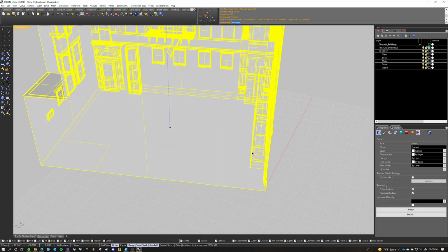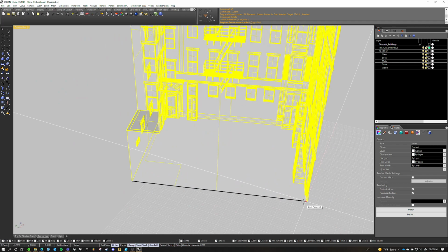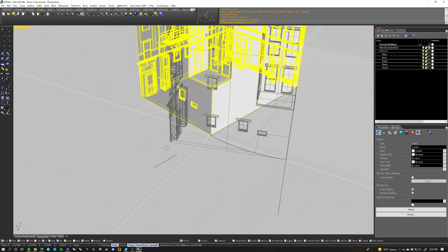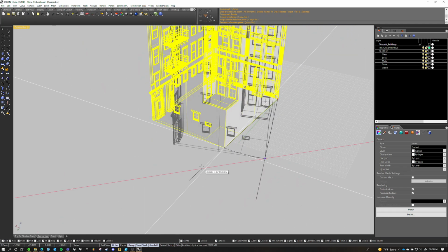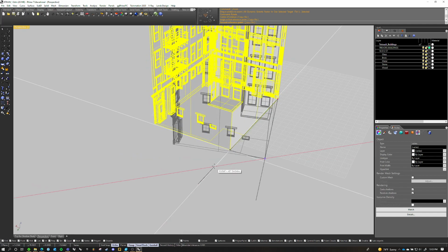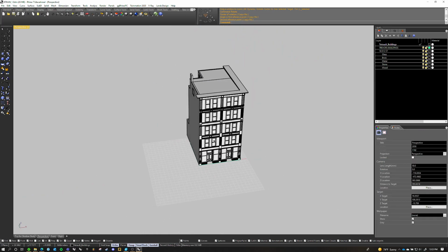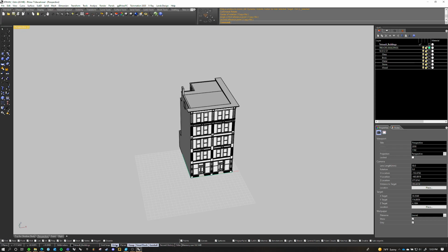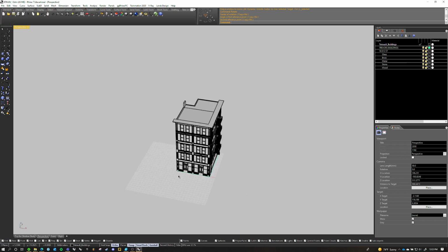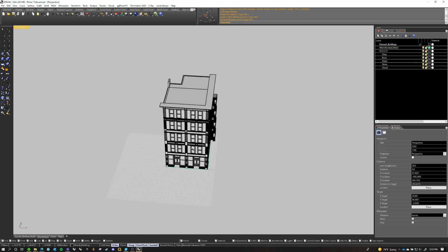And then we're going to rotate the building by typing in rotate into the command prompt, choosing the origin point, and then choosing the back of the wall maybe, so that we can orient in the right direction. Now I have all these different lines. It's just for me to line stuff up. If you want those, I can show you how to do that, but if not, you don't really need to worry about that. Down here I have ortho on, which is how it was snapping to the 90 degrees. And now it's in the proper orientation.